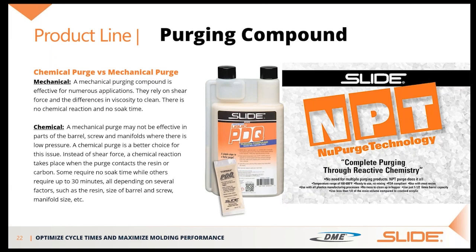So it's way more thorough than a mechanical purge. A mechanical purge can't work backwards like a chemical purge can, as far as that screw turning. So those flights will have buildup on them, and there's only so much you can do with mechanical purge.